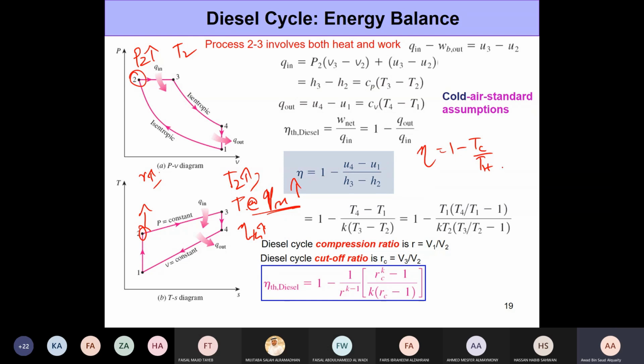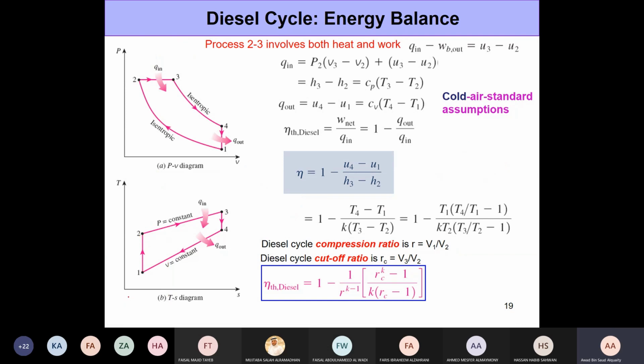By increasing the pressure, what we are simply doing is we are increasing the Th. Okay, so if you increase Th, of course, the thermal efficiency would go up. Now, of course, here we are dealing with a Diesel cycle, not with the Carnot cycle. So the amount by which it goes up would be different, but essentially is the same idea, right? So if you increase the temperature of heat addition, no matter what cycle you're dealing with, the efficiency would certainly go up.